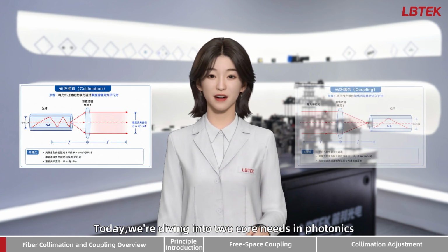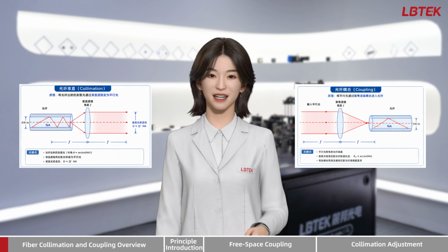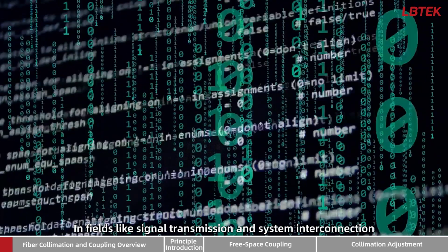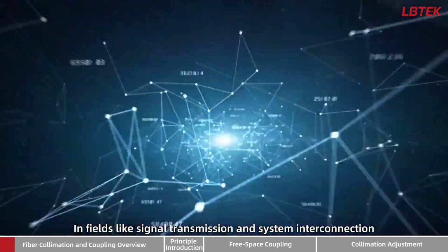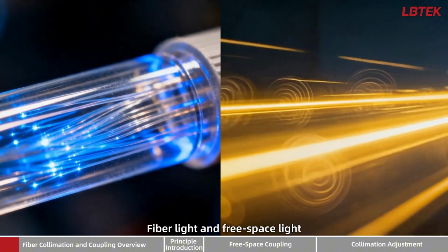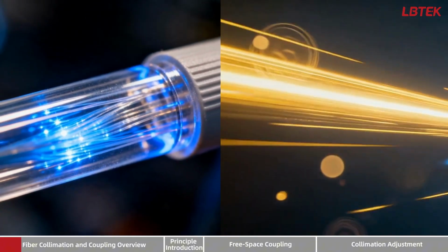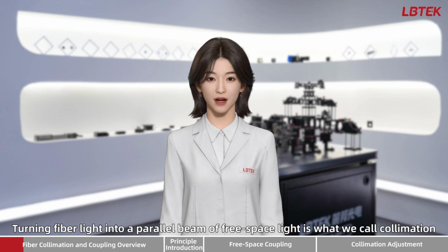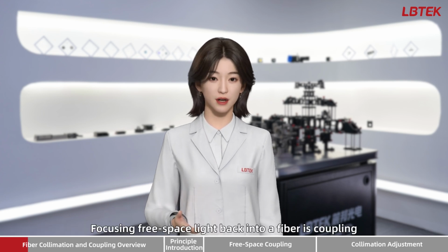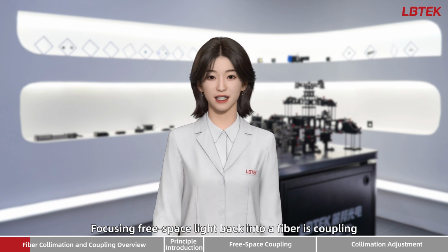Today, we're diving into two core needs in photonics: fiber collimation and fiber coupling. In fields like signal transmission and system interconnection, we often have to handle two types of light: fiber light and free space light. Turning fiber light into a parallel beam of free space light is what we call collimation. Focusing free space light back into a fiber is coupling.